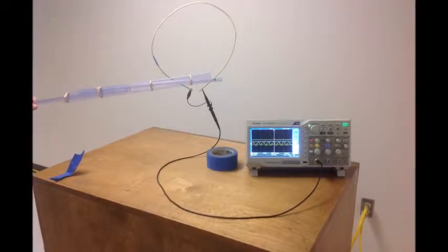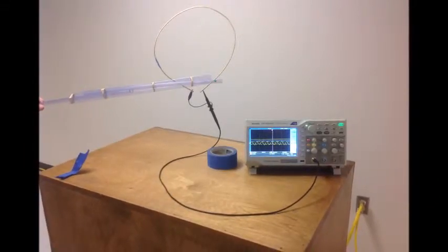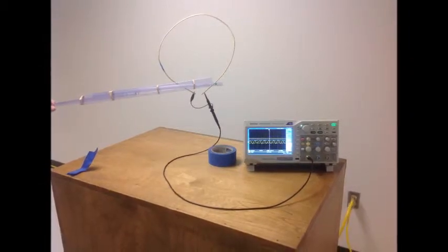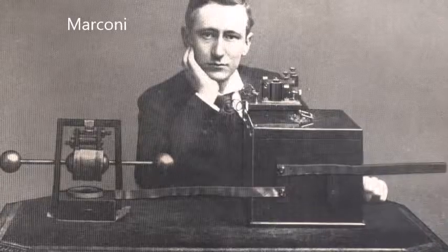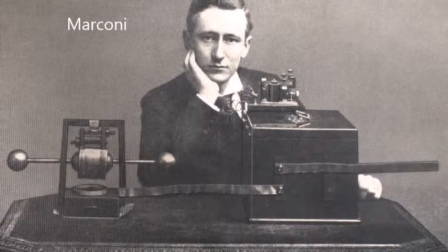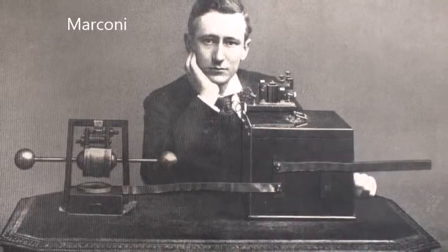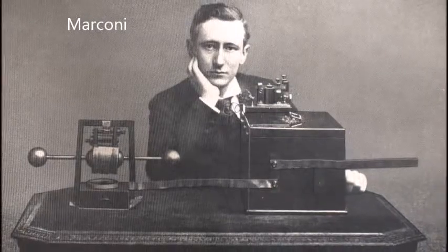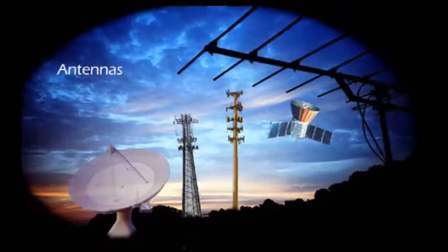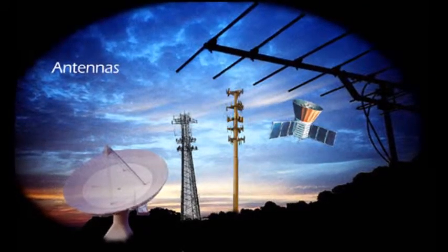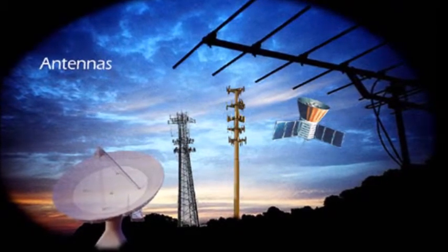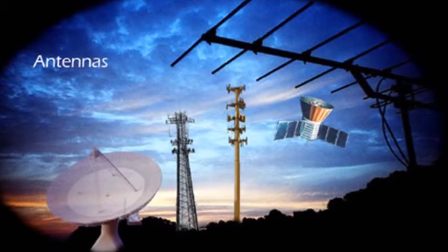This experiment tested the skills of finding a resonant frequency between the two Marconi antennas. We related the varying distances, moving the antennas closer or farther away, to the voltage peak to peak seen in the oscilloscope. The loop design aspect of the experiment proved to be the most difficult due to finding a proper method to increase or decrease the gap without interfering with the signal. Overall, our experiment proved to further justify Hertz's experiment by finding the resonant frequency between our two antennas.